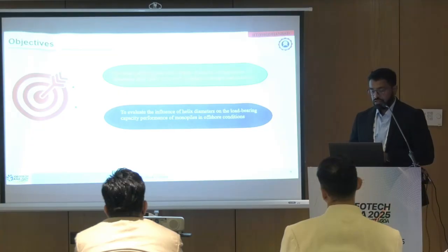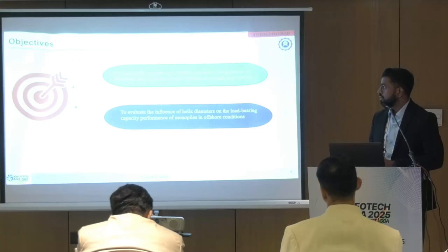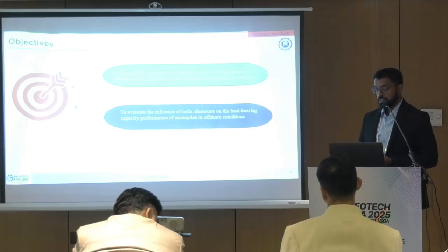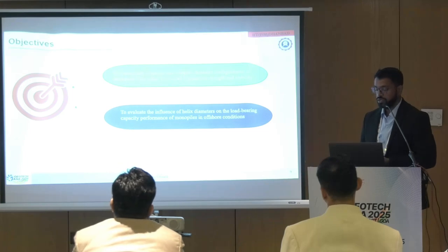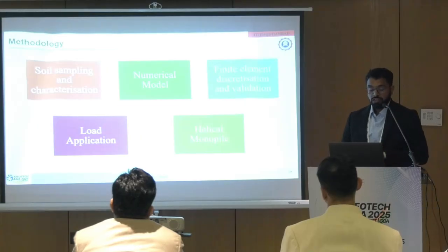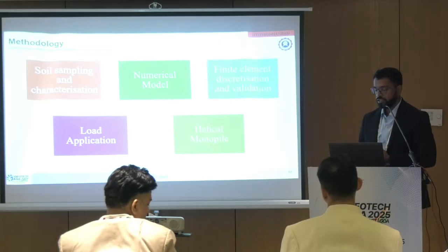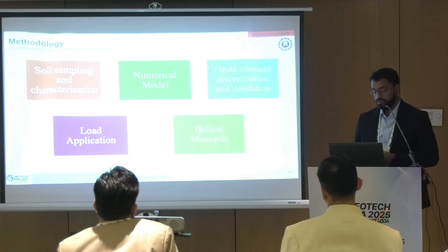So based on that, we have two objectives. First, to systematically simulate and compare diameter configurations and determine their effect on overall foundation strength. Another is to evaluate the influence of helix diameter on the load bearing capacity performance of monopile in offshore conditions. So the methodology is soil sampling and characterization, numerical modeling with finite element discretization, and load applied on monopile and helical monopile.